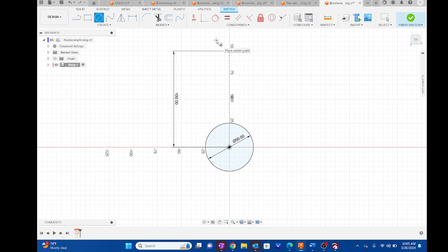And then I'm going to get another circle, hit X to get out of construction line. I'm going to put a circle here. We'll just make that say 20 for now. Whoops. Okay, I fell out of that. So if you do slip out of that, you can double click on it, go to your dimension tool, click on it, and then type in 20, enter, okay?